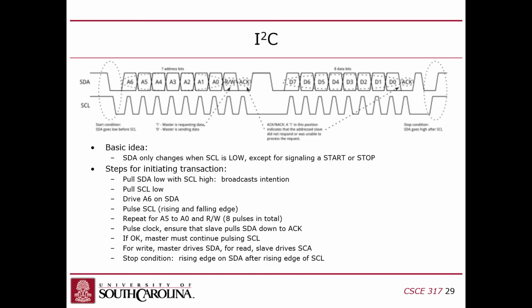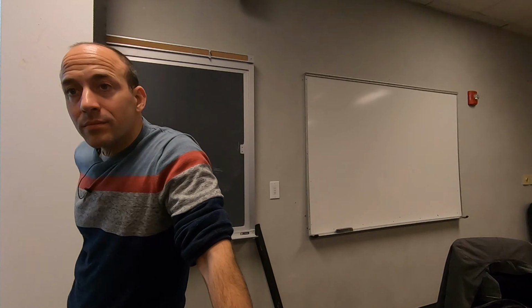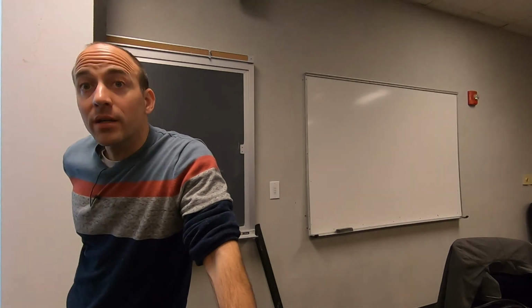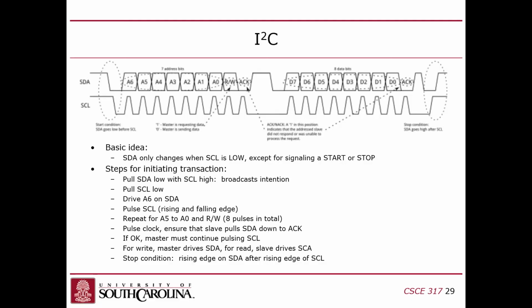Yes? Does this almost synchronize it, in the sense that in the last lab a lot of us had baud rate issues where we would send and receive at different rates? Yeah. So it's synchronous, just like SPI. You have a clock. The difference is that it's not an edge clock. It's a level clock. It's a pulsing clock, as opposed to a clock where you're dealing with the edges.